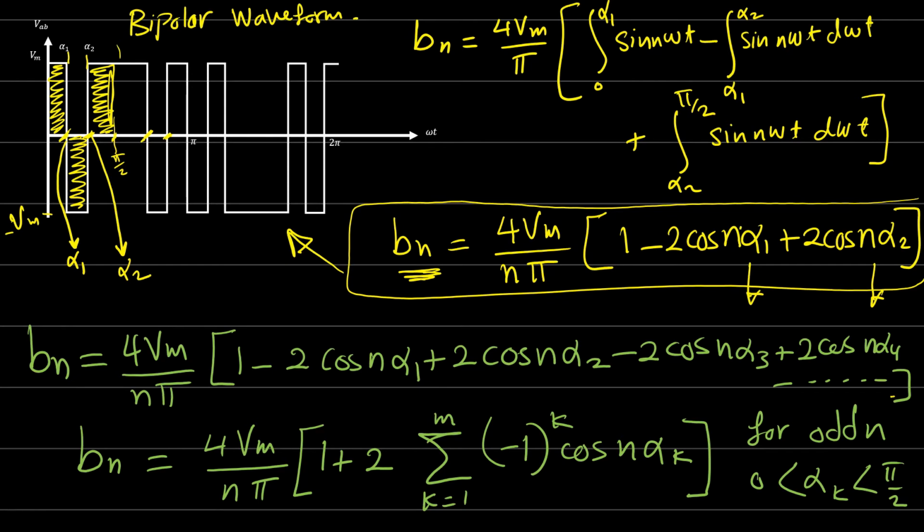And since, let's say for example, we eliminated the third and fifth harmonics, we can use a very simple filter at the end. Yes, we have a chopped waveform, but this waveform has the fundamental frequency plus the seventh harmonic, which is far away from the first harmonic. So we can use a very simple, small filter to reject these high order frequencies.